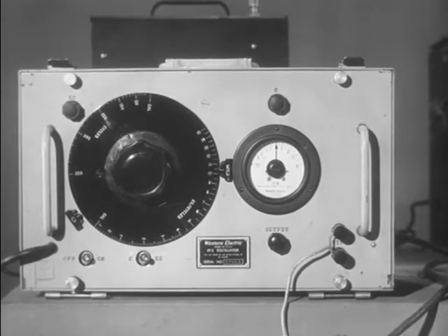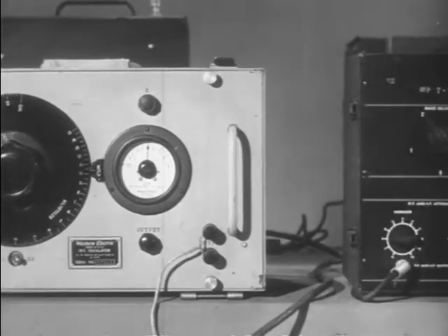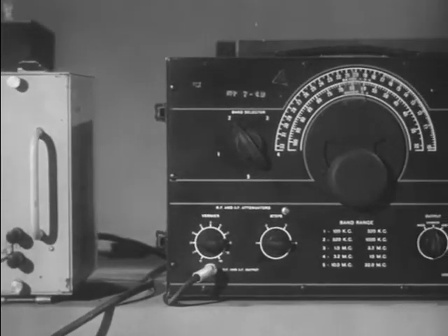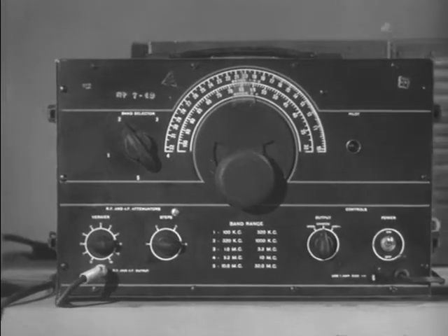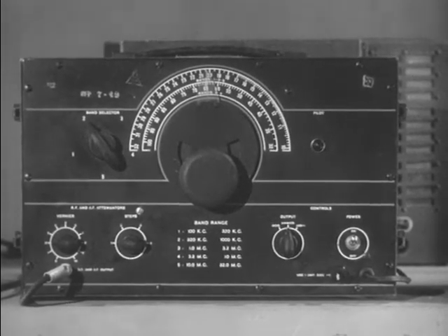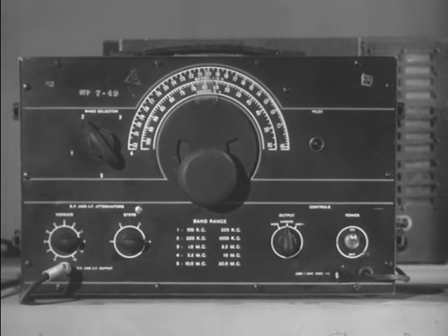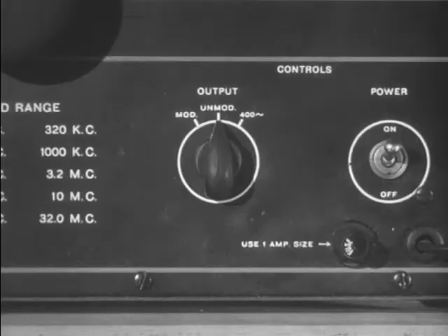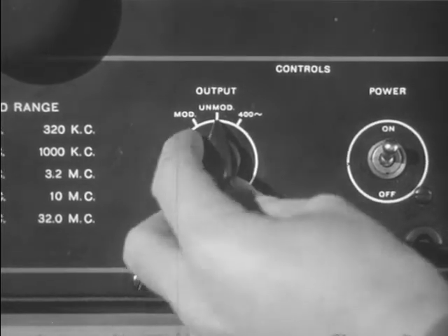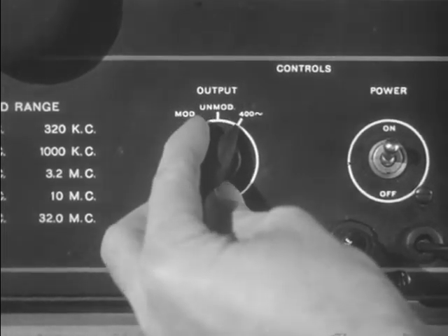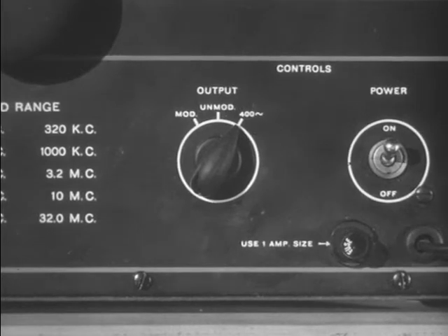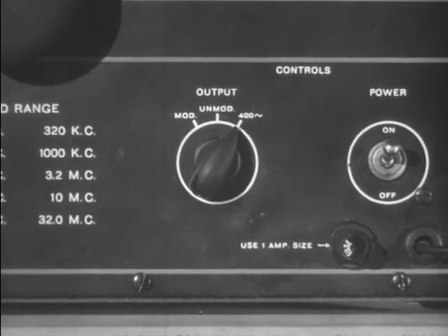In a great many audio frequency tests, a variable frequency oscillator is not essential. Because one audio frequency is usually sufficient for the necessary tests, most radio frequency signal generators include one audio frequency, normally 400 cycles. This makes the use of separate audio signal generators unnecessary, except for highly specialized work.